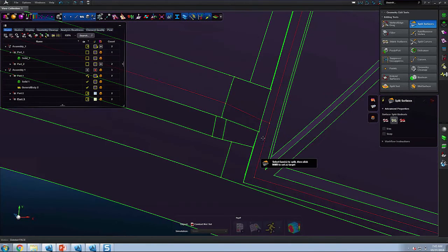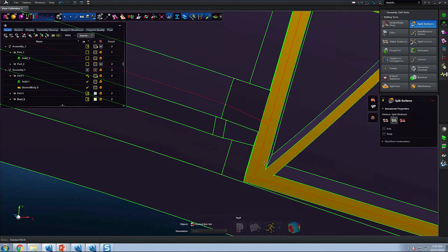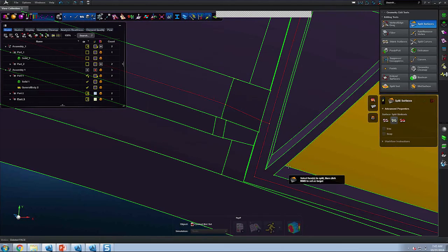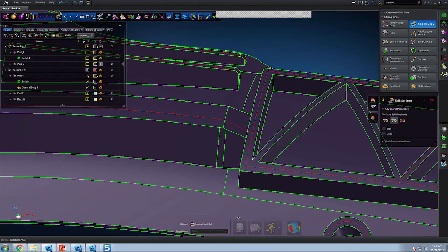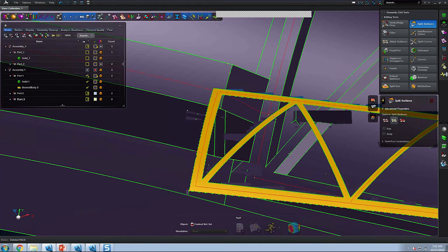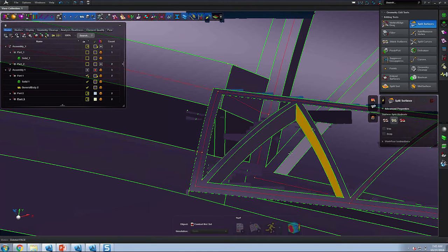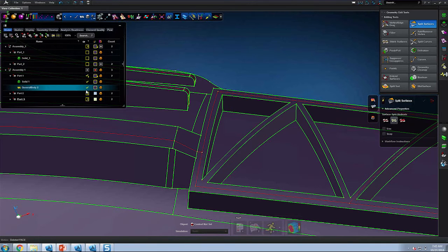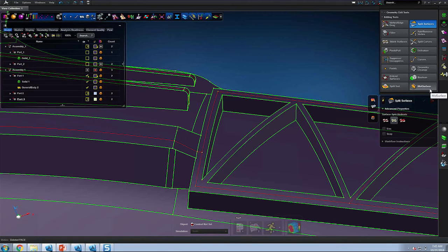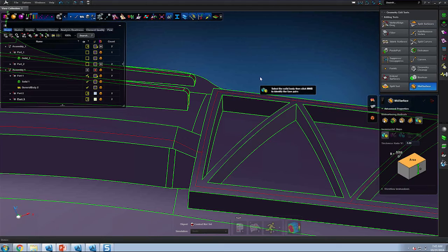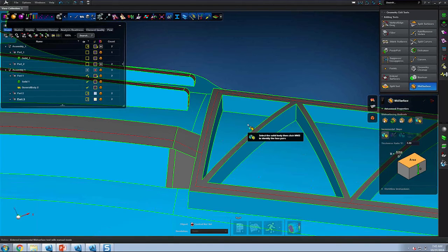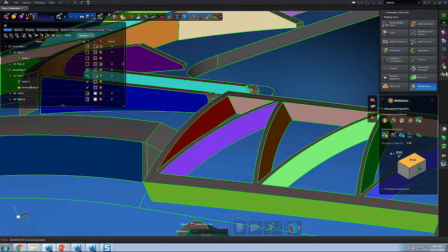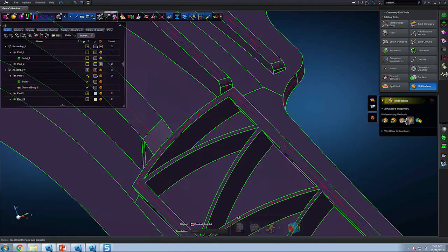Here in yellow, you can act as if this is the midline for the mid-surface, and here you see that we've done a great job of creating this mid-surface geometry. All that's left is to create the geometry for these ribs that you see me highlighting on the screen. I think I'll take time right now to do this. So let's jump back to our semi-automatic tool and display our color-coded pairs again. Or actually, let me use the manual approach.